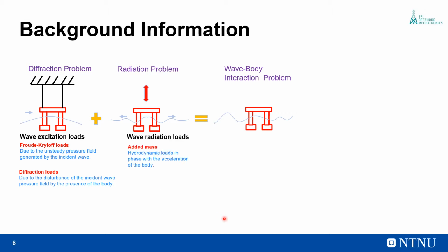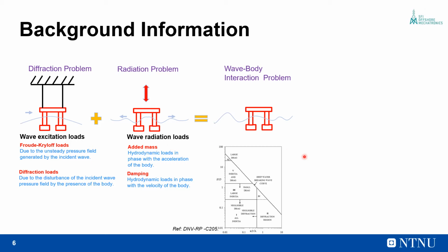Considering the loads exerted on the body by the radiated waves, the component of that hydrodynamic load which is in phase with the acceleration of the body is called added mass, and the component that is in phase with the velocity of the body is called damping.